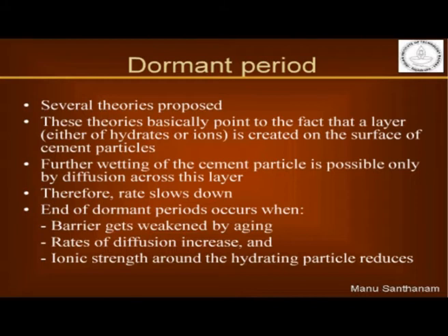And it happens because when you're mixing cement with water, you form this initial hydrate layer which sort of slows down the reaction. Okay, and that is very crucial for us because we get the time required to actually work with the concrete. There are several theories that you can actually read in the slides on your own. It's not really something that we need to be concerned with, but the fact that it really contributes to the overall performance of the concrete is what is important for us.